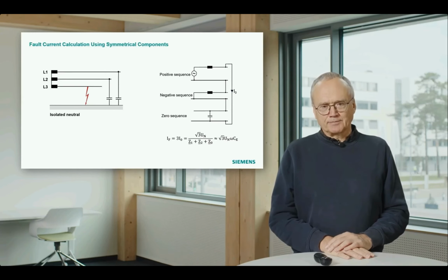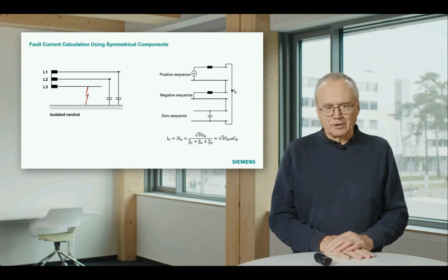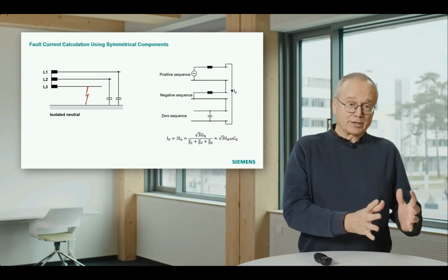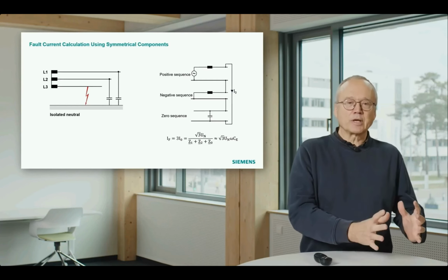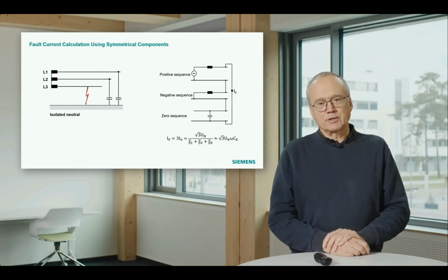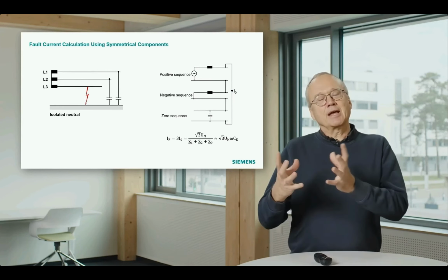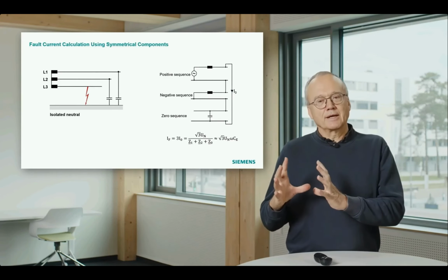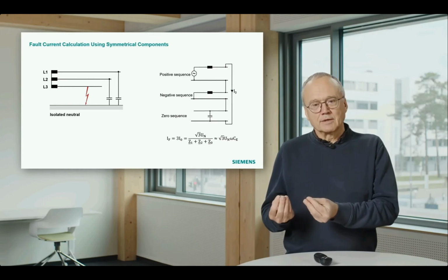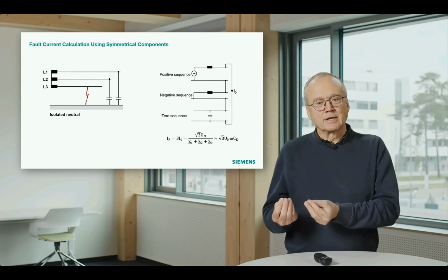And for that reason, it's a common way of practice to use the so-called symmetrical components. That means you do a mathematical transformation from this real world into the world of symmetrical components you see on the right side. And there you get an equivalent circuit for that, which can be simply calculated.